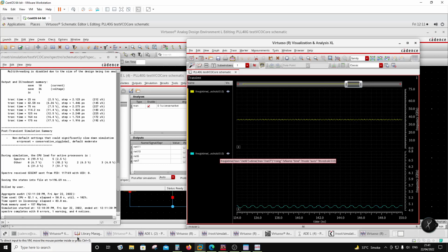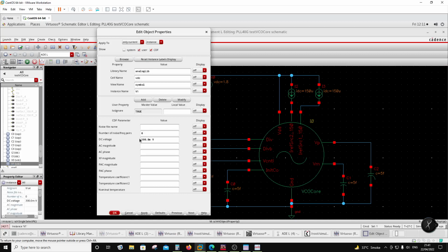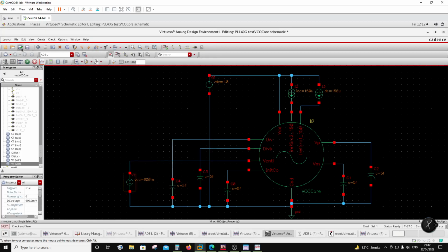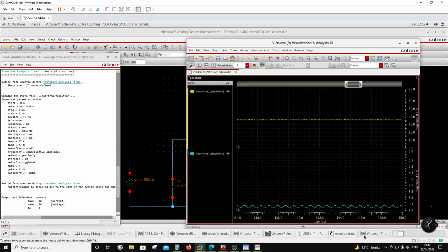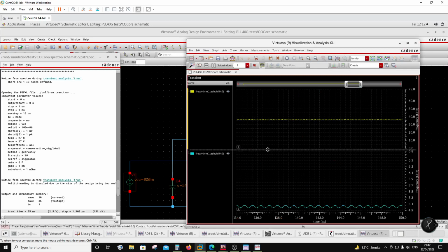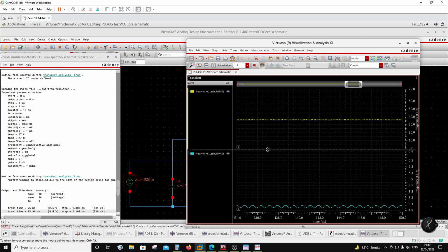This is 36.17. So basically we don't go down to this voltage. Let's change this to something like 0.6. Okay, 0.6 is good enough. The gyrations you are seeing are because we have gone far below in frequency. Check and save, simulate. So basically the injection lock loop has a range. So you will typically start seeing this lock falling off, and you will see these gyrations.